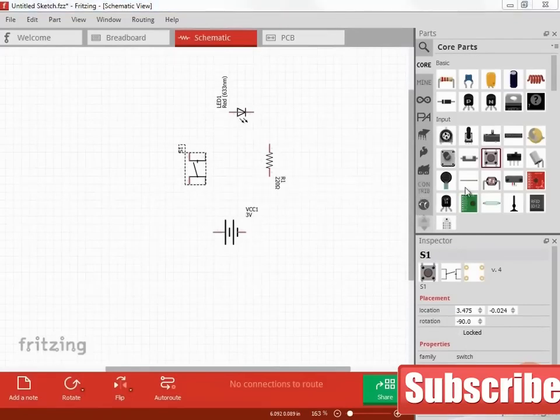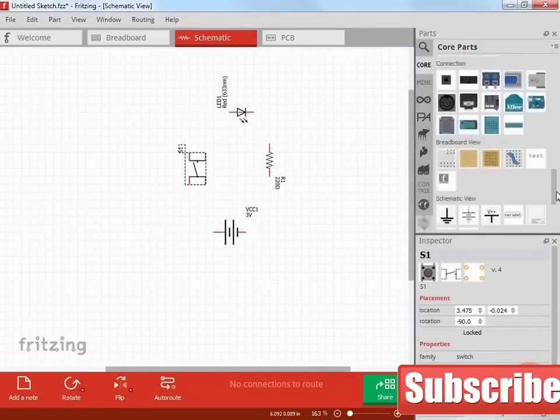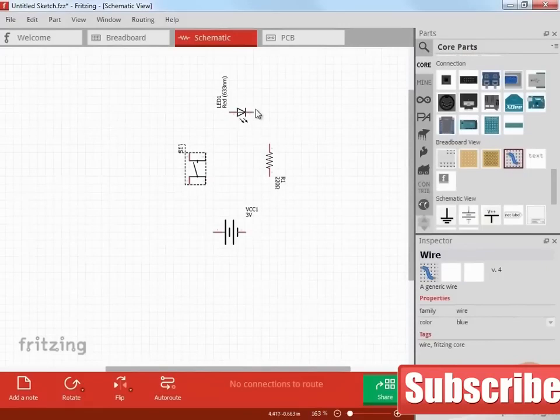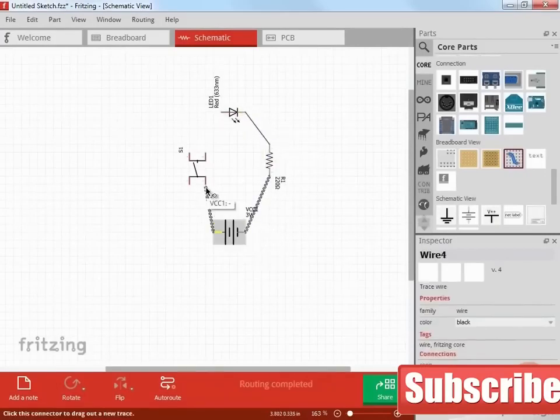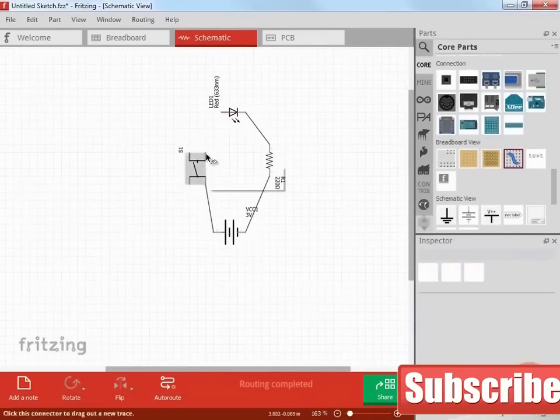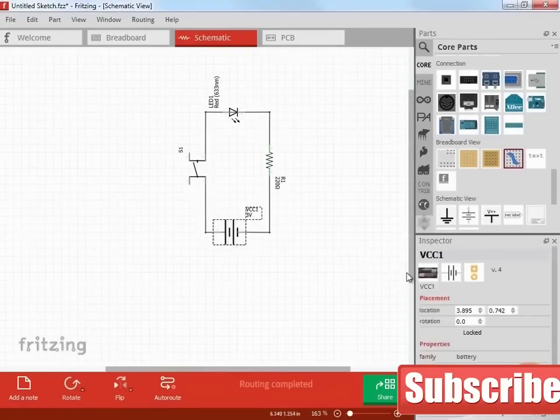Now we'll need to connect the components, so let's go to our parts list and look for the wire. Select our wire, and we'll make our connections. Now that we have our circuit all wired up, we need to select the properties of each component. We'd like to use a 9-volt battery, and the library defaults to a 3-volt battery, so we'll go to the properties for that. We'll select our 9-volt battery.